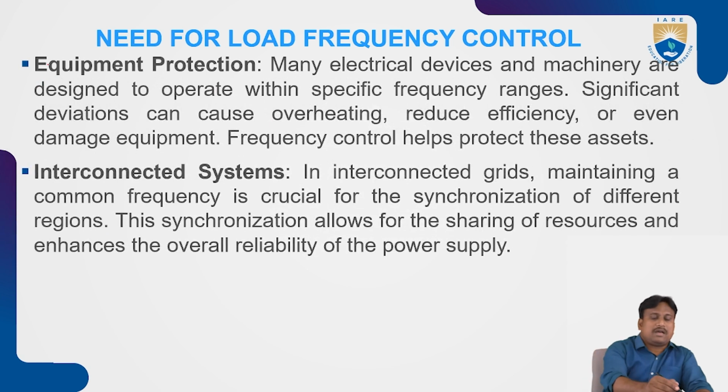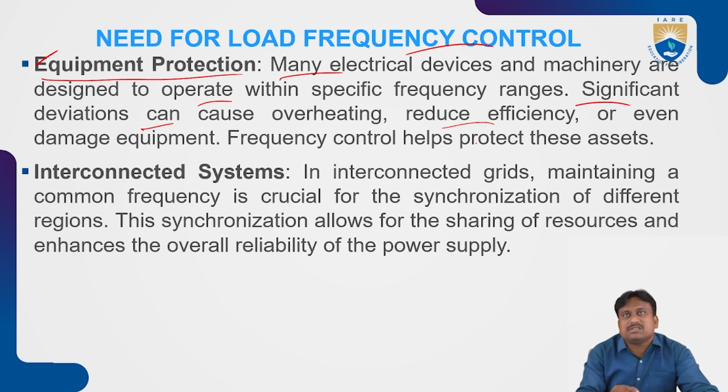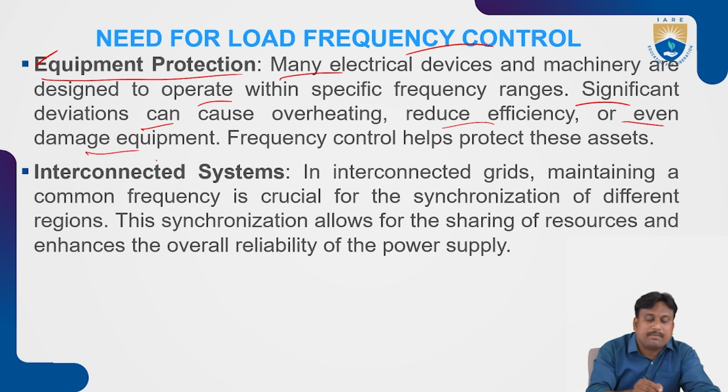So here, one of the most important factors we need to consider under these conditions of operating load frequency control is equipment protection. So what does this equipment protection mean? Many electrical devices and machineries are designed to operate within specific frequency ranges. Significant deviations may cause overheating, reduce the efficiency of the system, or even damage the equipment. So this leads to frequency control to protect these assets.